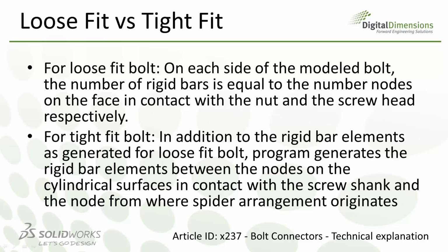And now, moving forward, let's take a look at one of the other conditions. Within the SOLIDWORKS options, we also have the ability to define a tight fit condition. Each bolt is defined as either loose fit or tight fit. For the loose fit, the bolts are modeled with only end caps and a rigid contact set between each cap. For the tight fit bolt, rigid caps are applied on each end of the model.